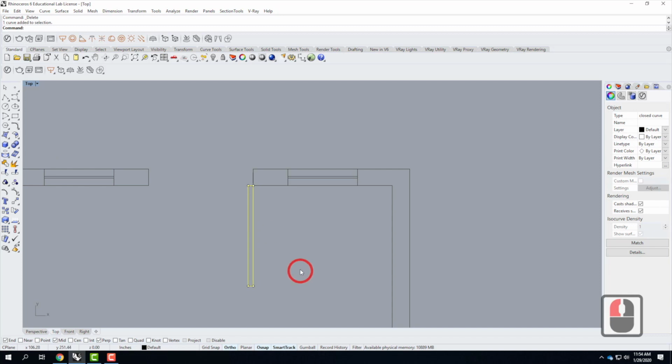Okay, so I have that door. Next thing I need is the door swing. I need to use a curve tool for that. So I'm right here. It's an arc. Now this center, start, and angle I find really difficult to work with. So I'm going to use one of the tools underneath there for the arc, and it's this one. It's start, end, and direction at start. It doesn't matter whether it's direction at start or direction at end.